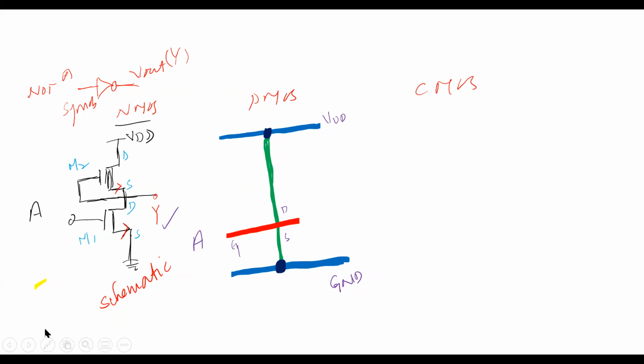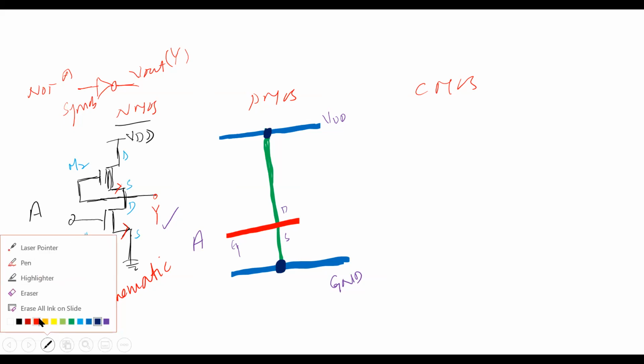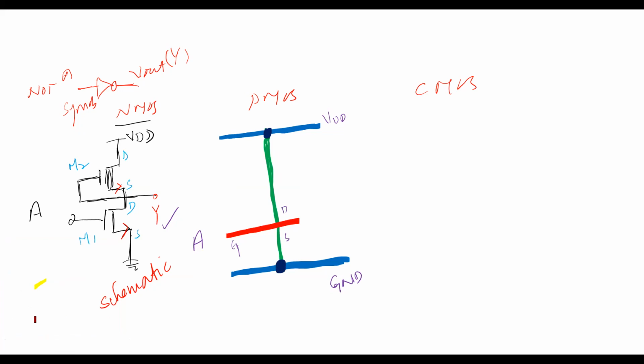The second thing is the second transistor, the M2 transistor. The N diffusion layer is already there. We need to run polysilicon over that. This is my polysilicon. This is my polysilicon. The gate is again joined to the source, so take it like this. Understand? Yes, sir.